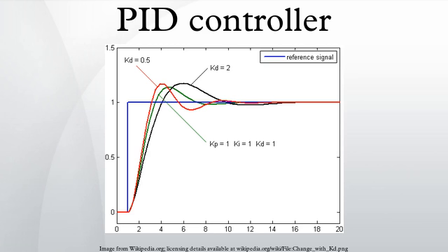Setpoint weighting. Setpoint weighting uses different multipliers for the set point and the error in the proportional and derivative element of the controller. The error in the integral term must be the true control error to avoid steady-state control errors. These two extra parameters do not affect the response to load disturbances and measurement noise and can be tuned to improve the controller's setpoint response.